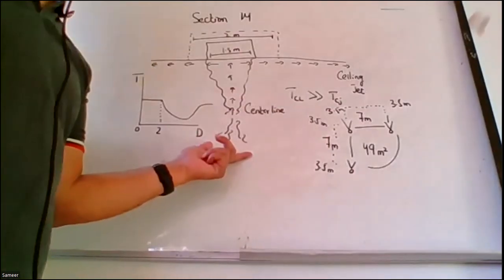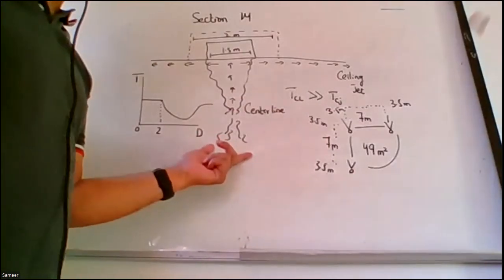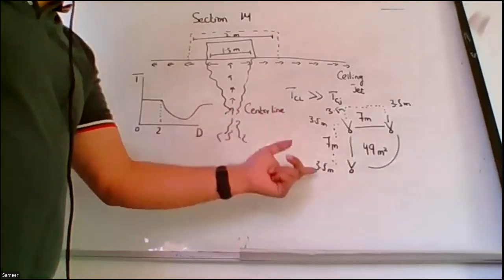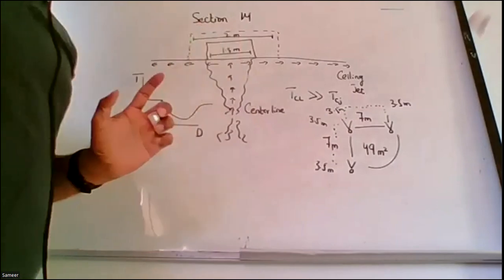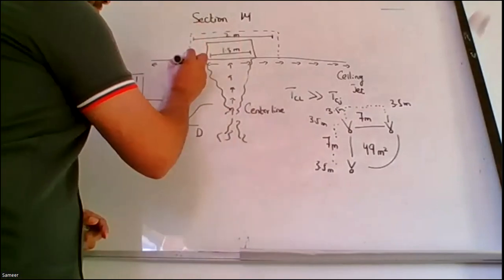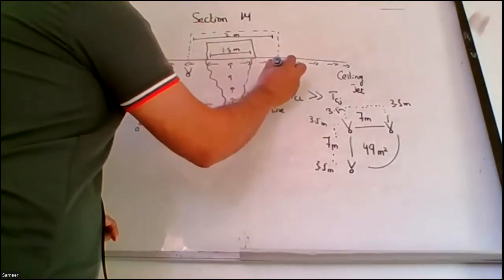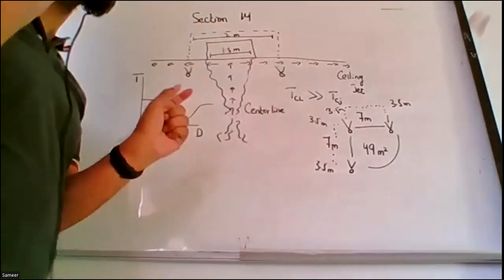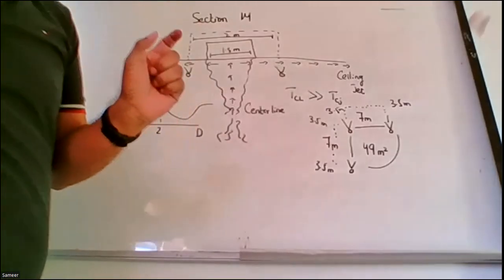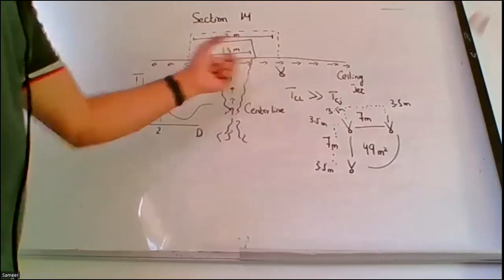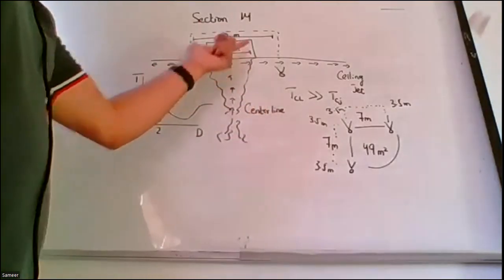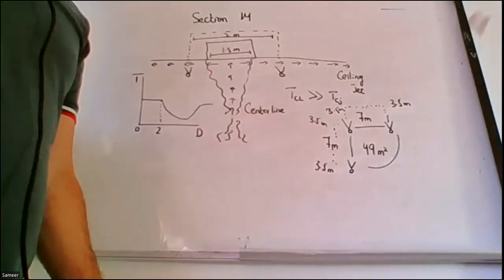Flame can appear anywhere in the room. But what I want is that within every 3.5 meters, my detector should be available. That is why the distance of heat detectors is always specified by the manufacturer, because the total area of effectiveness is 3.5 meters.